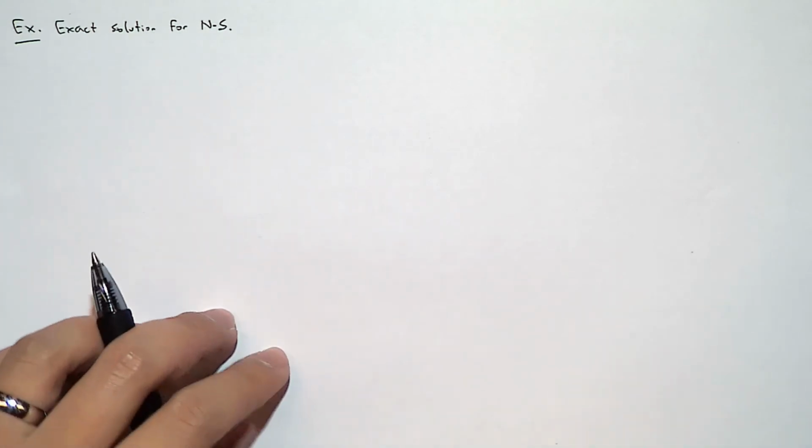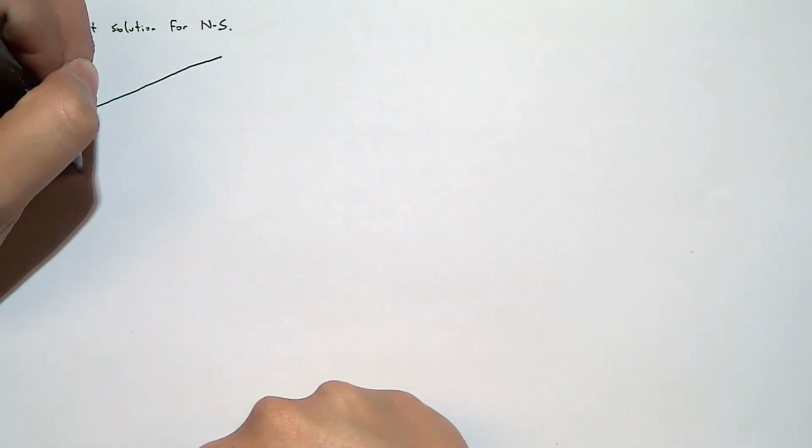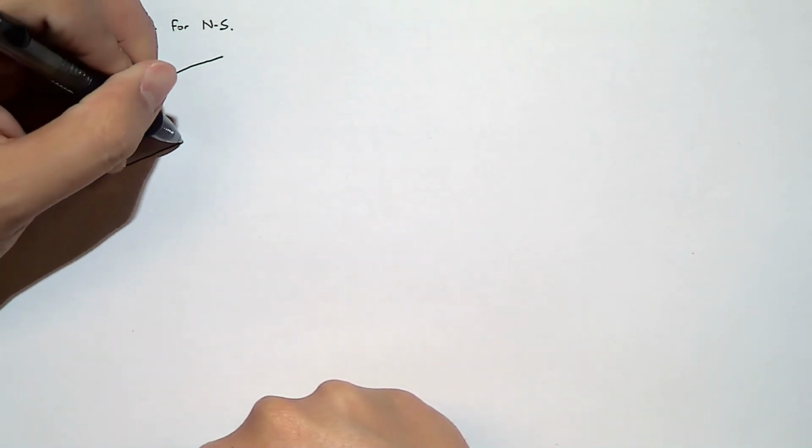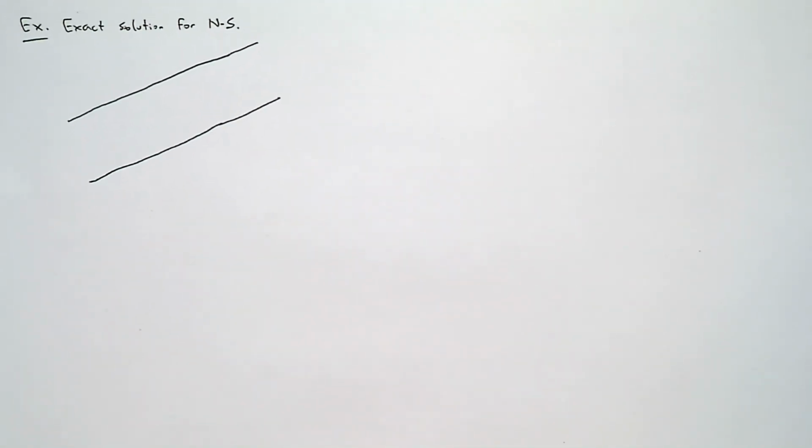Let's say that we have flow traveling through what's called a channel. And here I want to make an observation I made this semester. Us civil engineers, we define channels as boundaries that bound the flow on its bottom and sides, typically open to the atmosphere.